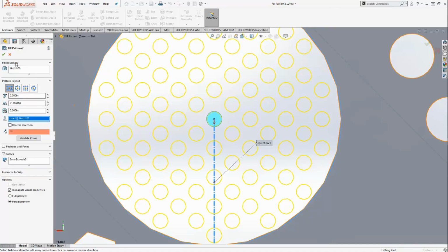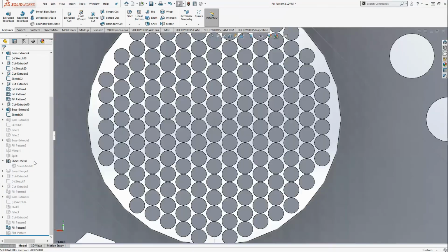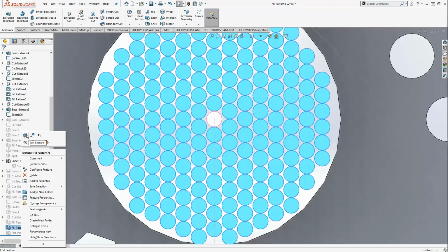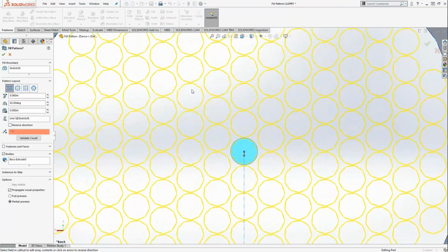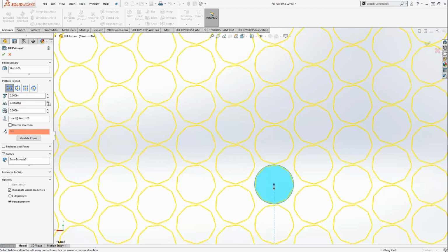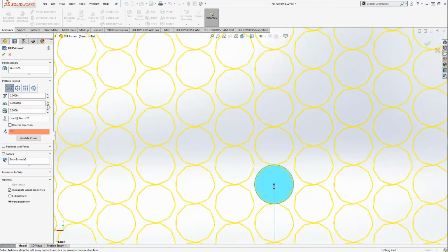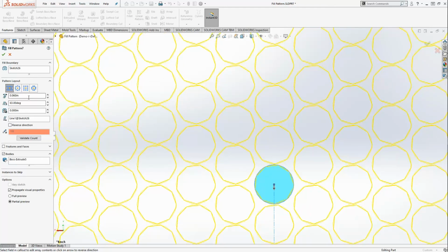And in the case that I had previously, what I had done is I had taken the fill pattern and made them as close as possible without adjusting the spacing too much. So as you can see, I used the angle to control how close these bodies were. And then once I did that, I started messing with the spacing over here.